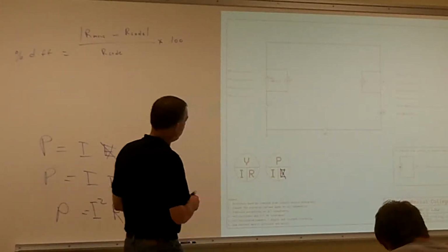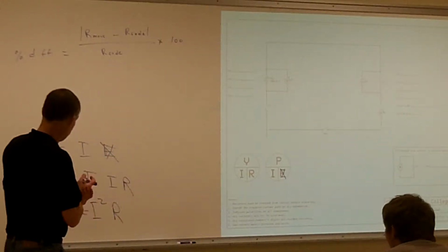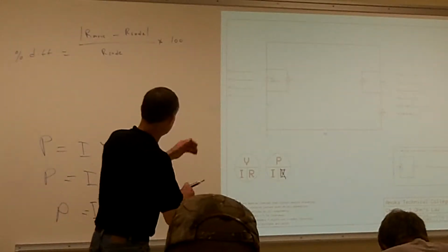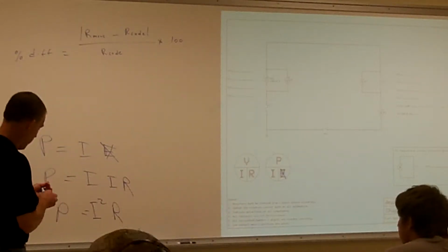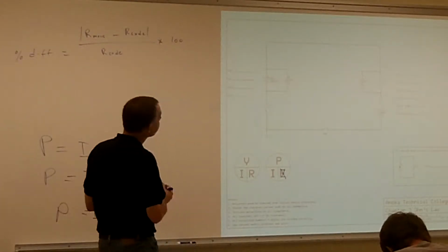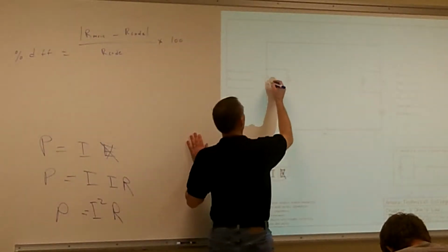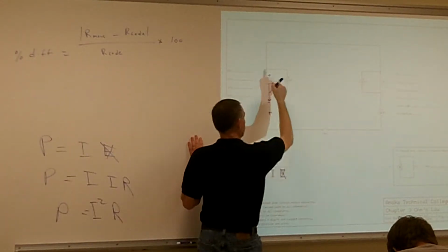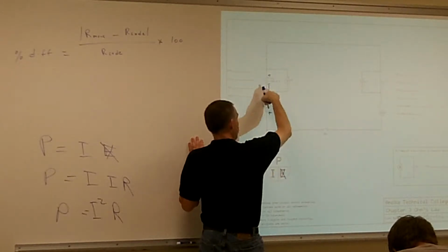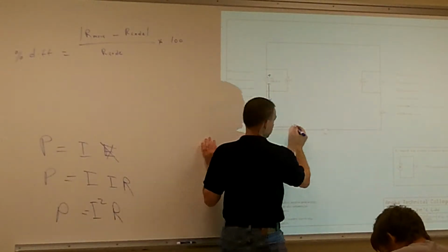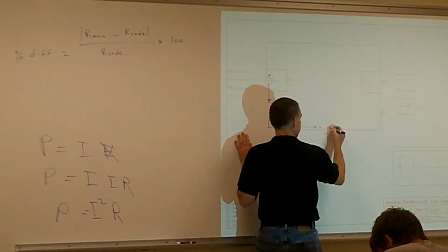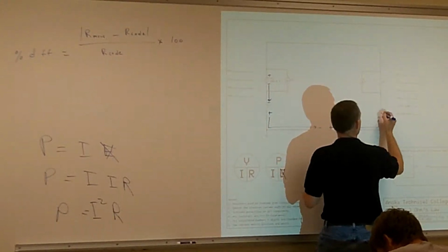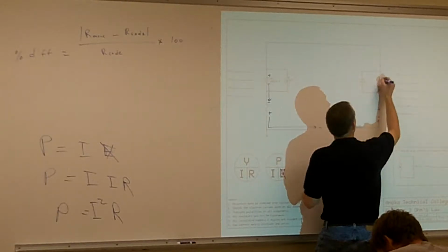Alright, let's start analyzing this circuit, first analyzing it and then we'll talk about the power. What's the first step I want to do? Draw my electron current path. It's going to come down, and I put my polarities across each of my components, so as it goes through, this side is always more negative than this side. Go through the switch, more negative than this side. Do my current meter, more negative, positive, more negative, positive.